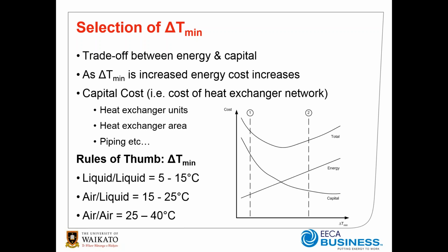This concept of the minimum approach temperature shouldn't be confused with heat exchanger sizing methods. In this case, we're applying a very simple test and measure in order to adjust what levels of heat recovery we get in order to do a rough optimization of cost.